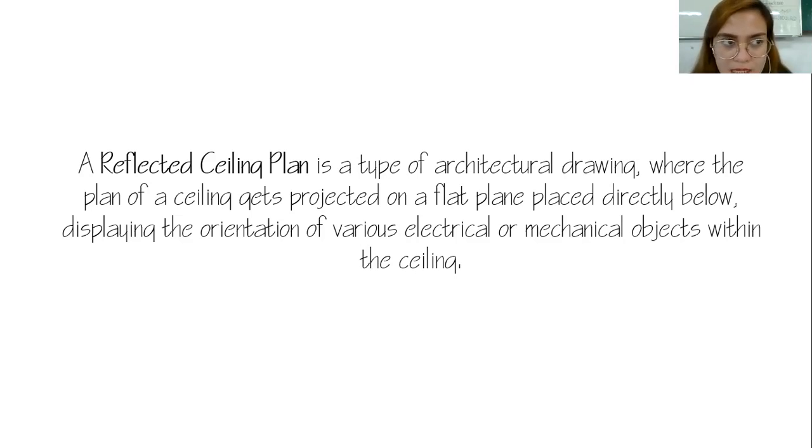So the reflected ceiling plan is a projection of your ceiling onto your floor plan. You're going to use the floor plan, but you're going to locate the placements of the lighting fixtures and other equipment that you'll be using on your ceiling.